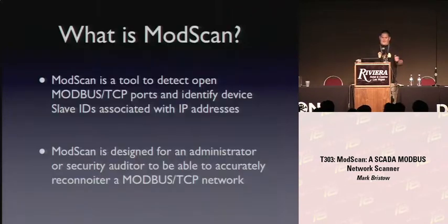So, ModScan. We're not here to talk about SCADA architecture. I just need to give you a primer. What is ModScan? ModScan is basically a tool that I wrote to detect open Modbus TCP ports and then identify these things called slave IDs, because you can't address any device without knowing its slave ID. And then you need to associate that with an IP address. Well, that's what ModScan does, at least today.